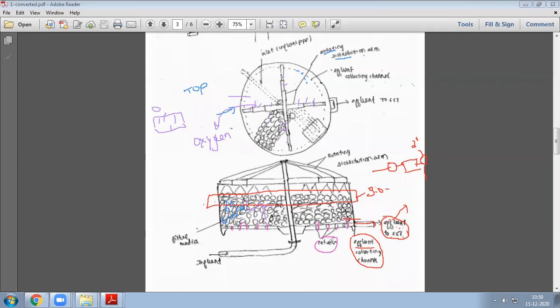So here, these laterals do not get exhausted. All the waste is percolating, right? All the waste, as pure water, will reach here through this lateral, and it will have some slope like this. Because of this lateral it will be collected and move to the main chamber, and then it will be collected in the effluent tank. That is the function of these laterals.